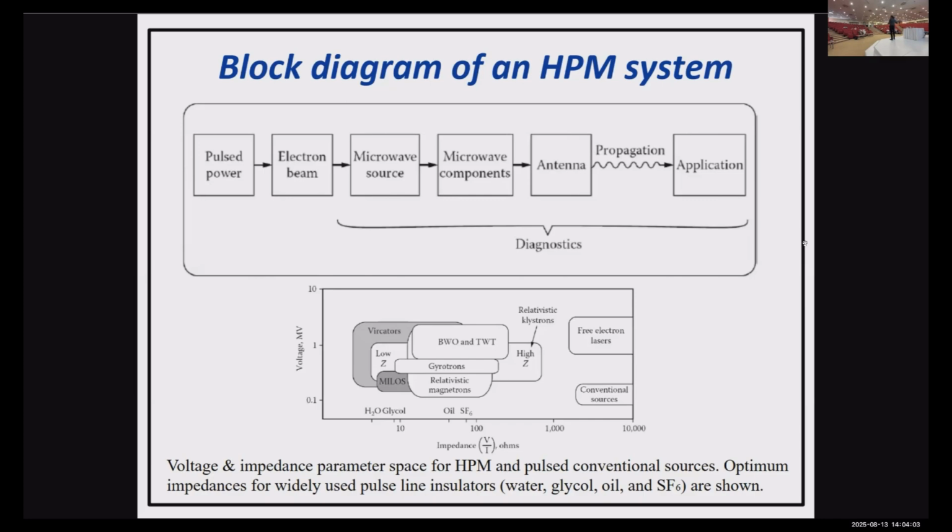This is because you don't want to have multiple electrodes. You saw this morning, to design an electron gun, you need some ceramic and then another electrode, a focusing electrode. You don't want all of this because you are talking about kiloamps of current. That's a lot of current. And whenever you have small gaps, you end up with arcing. So you're not going to be using the electron gun efficiently. Thermionic emission cannot give you that range of current. I will show you the next table.